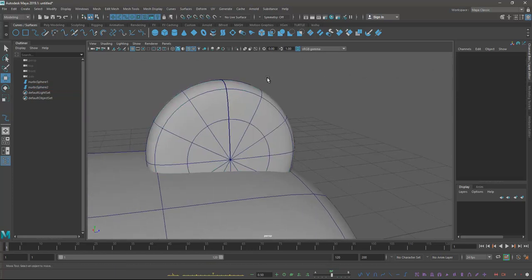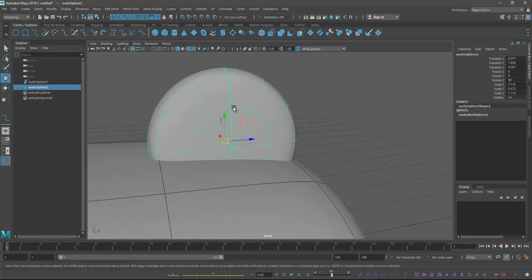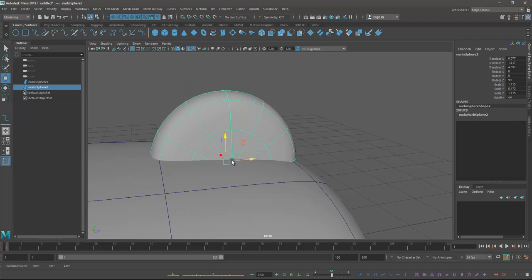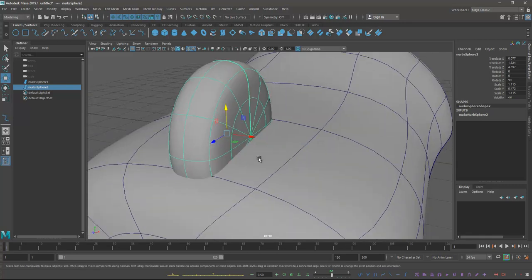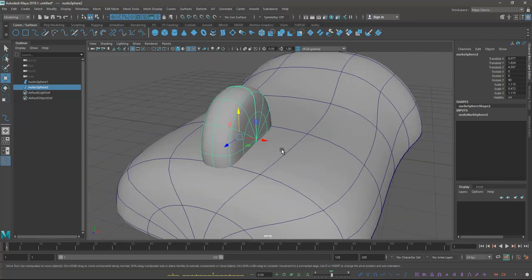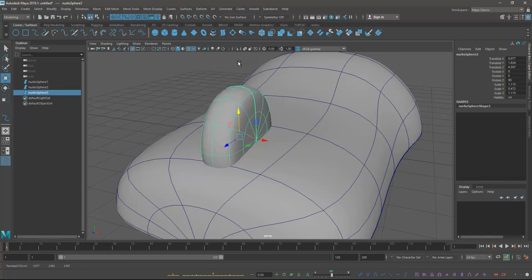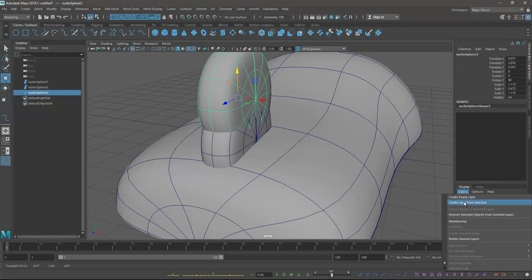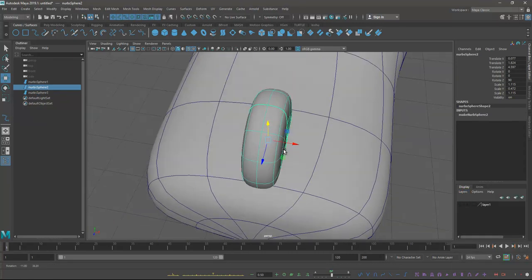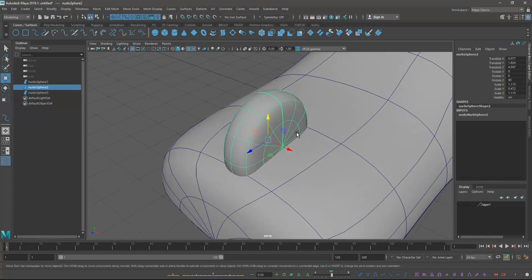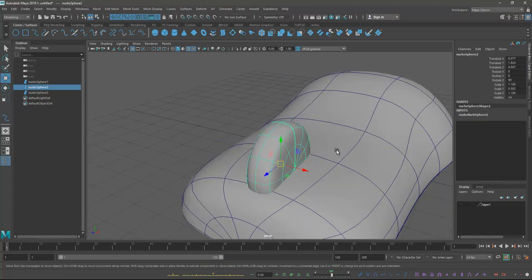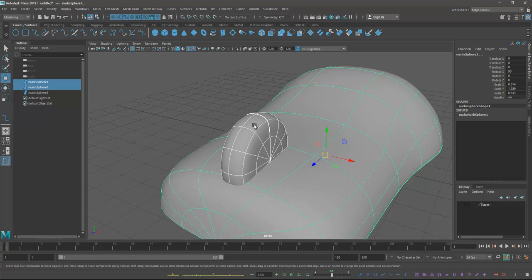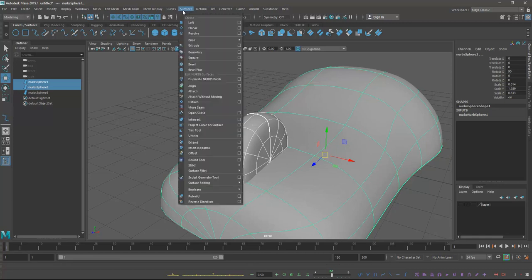So this is the seam line, right? The thicker line, right? It should not be like this, it should be a little bit like this, because we are doing project curve on surface here. What I'm doing, I'm taking a duplicate of the same color, Control D, you can get it. Okay, keep this in a layer, hide it. And now just select both surfaces. So you can find something like insert.